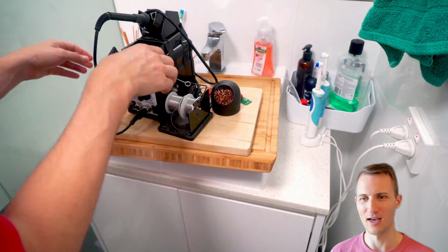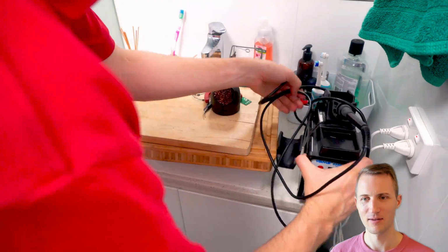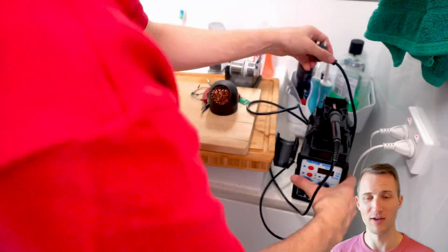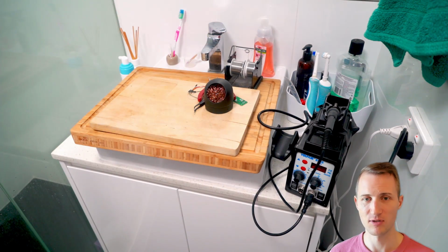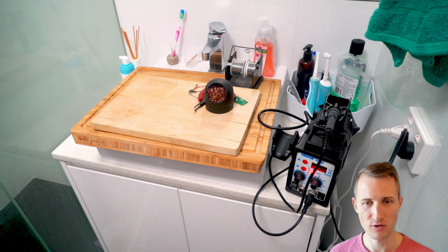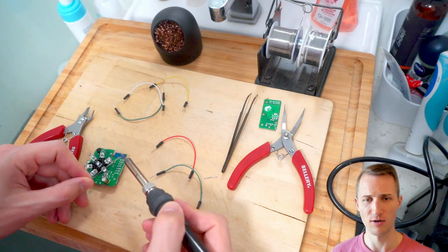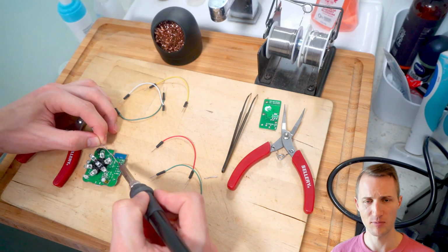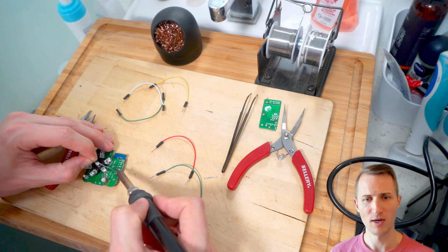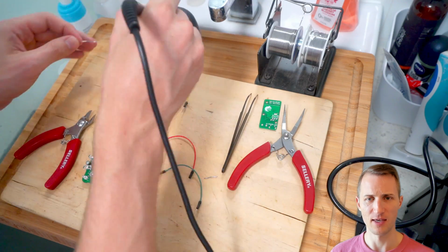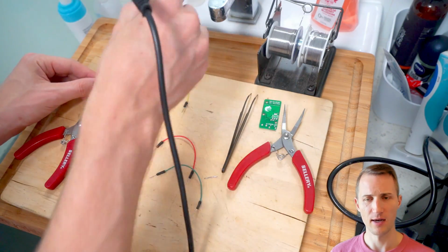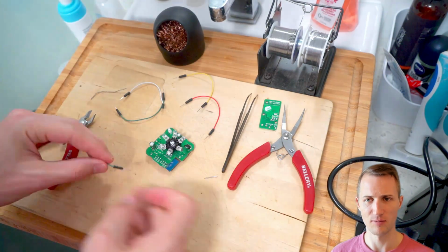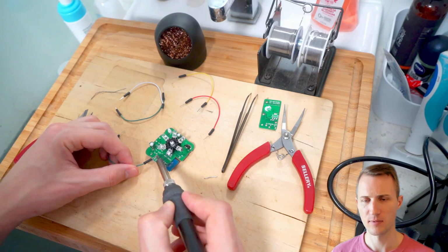In this case, I've got a soldering station with a temperature controller. Do this somewhere which is well ventilated, and I found a small tipped soldering iron was really handy. So firstly, I'm just going to put some blobs of solder on each of the pins that I'm going to connect up, which is not all of them. Once that's done, we're going to get some of these jumper leads or DuPont cables, as they're super easy to plug into pins on the controller.